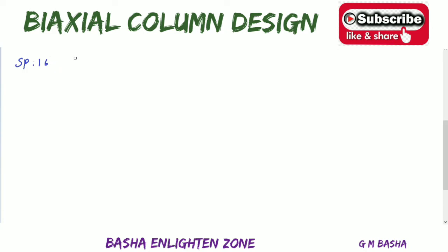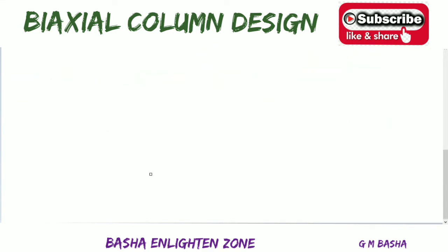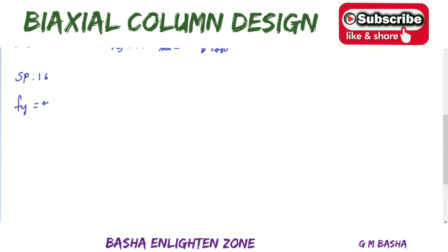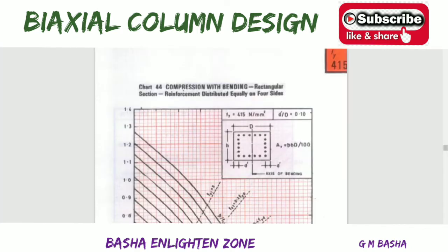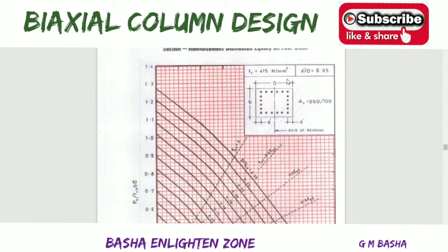So before going to the charts, first what you have to do is see the requirements in the question. So there will be fy 450 Newton per mm square. Okay, fy 450 Newton per mm square. And what do you still want for selecting a graph? So I will show you the graph here. So this is the SP16 chart number 43. I am just showing one example.